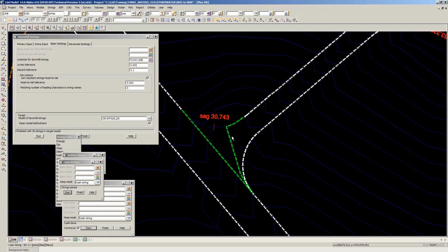It's really sheet flow and not worth modelling as overland flow or flooded width strings, I should say. What is important though is that anything that doesn't make it into the pit that we are proposing here is going to bypass and make it to that point, and it will convey the flow rate without necessarily seeing how it happens, because once you've got sheet flow, flooded widths are a bit meaningless.